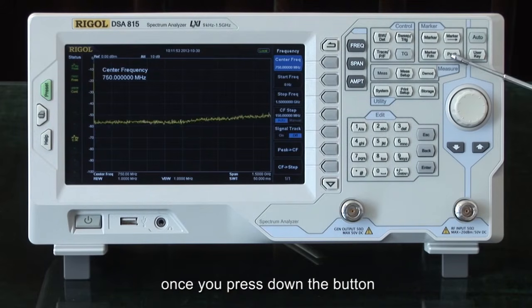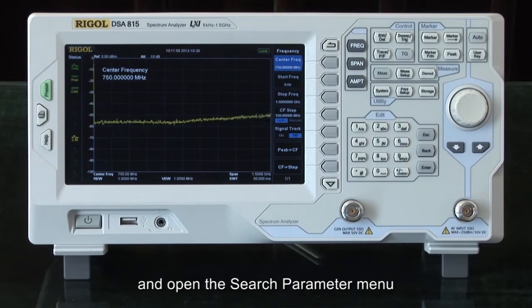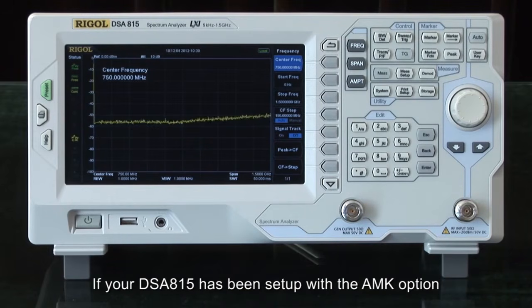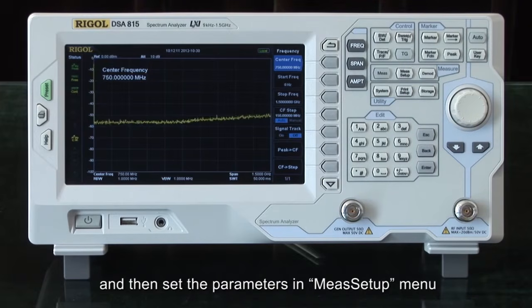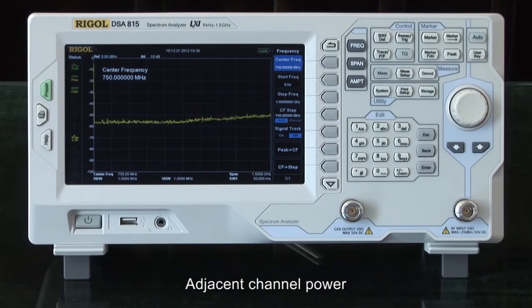For the peak function, once you press the down button, the analyzer will search the peak on the current trace and open the search parameter menu. There are also optional advanced measurement functions available. If your DSA815 has been set up with the AMK option, you can choose any of the functions and set the parameters in the Measure Setup menu. Press the Measure button, and we can see the advanced measurement functions: VSWR, total power, adjacent channel power, occupied bandwidth, emission bandwidth, carrier to noise ratio, harmonic distortion, and TOI.